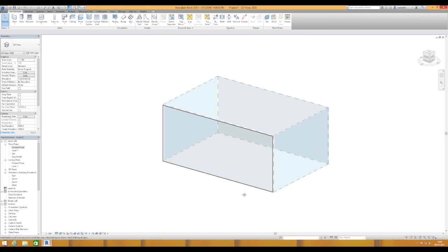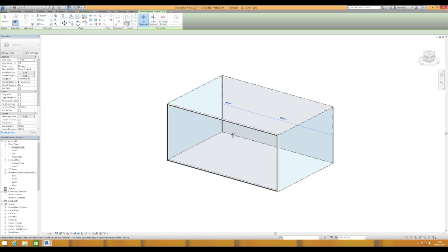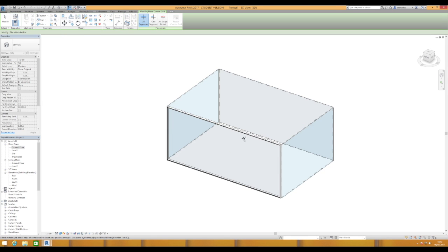If I was to divide that curtain wall up now, I could divide it using a curtain grid. Quite often I'll divide, if you hover along the edge of the curtain wall, you'll see that the snap seems to take over at a couple of places. It takes over at, it's saying here to me, 1/3 or 2/3 of the curtain wall panel.